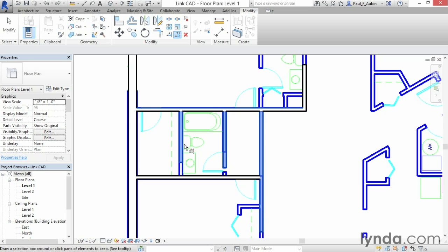You could see that all three of those walls would go across. Now, if I reset again, click this one, and then click here, notice that it will actually trim it back. So this command is both a trim and an extend command. And if I drag through these two, the boundary edge was still active, and those two will extend out.